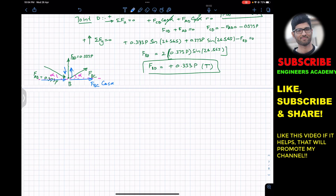So now if we apply the summation of forces along Y while considering joint B, the summation of forces along Y must equal 0. And this is our positive Y direction. So now we have FBD, that is plus 0.333P. Then we have this component of FAB, it is acting downward, that is minus 0.373P, and this is the sine component, sine of alpha, and alpha is 26.565.